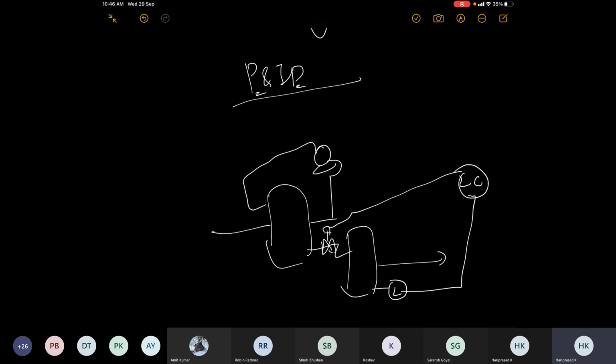The PFD is giving you high level information. Sometimes even licensors would give you the P&ID. It's up to us, depending on the contract that you're going to get agreed upon. But the PFD is very, very high level. The P&ID contains each and every detail, because this is a piping line, because for measuring the level, you have taken a piping line outside. And for instrumentation, there is a level sensor, and also going back over here. So this would be very comprehensive information.